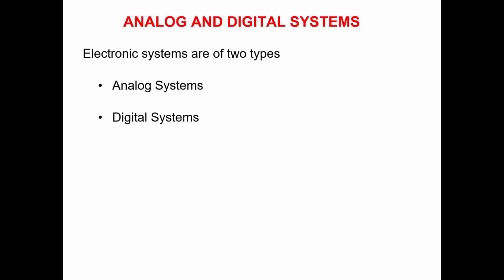Switching circuits may be a combinational switching circuit or a sequential switching circuit. In combinational switching circuits, the output depends only on the present inputs, whereas in the sequential switching circuits, the output depends on the present inputs as well as the past inputs. Digital circuits are also called logic circuits because each type of digital circuit obeys a certain set of logic rules. The manner in which the logic circuit responds to an input is referred to as the circuit's logic.